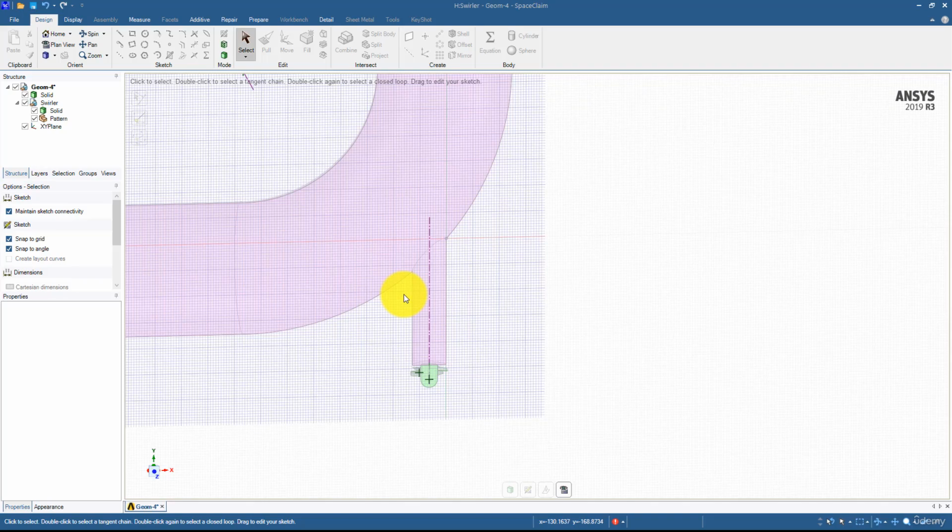And this is now very simple inside the workbench. You have to just create the model, and because we have already created models, you have to just combine them with the use of the assembly command and move them to the required location. Simply click on the mesh tab, and this will give you the option. Again, you don't have to start from scratch, and you can make the mesh in one or two clicks in a few seconds, and then move to the Fluent tab.